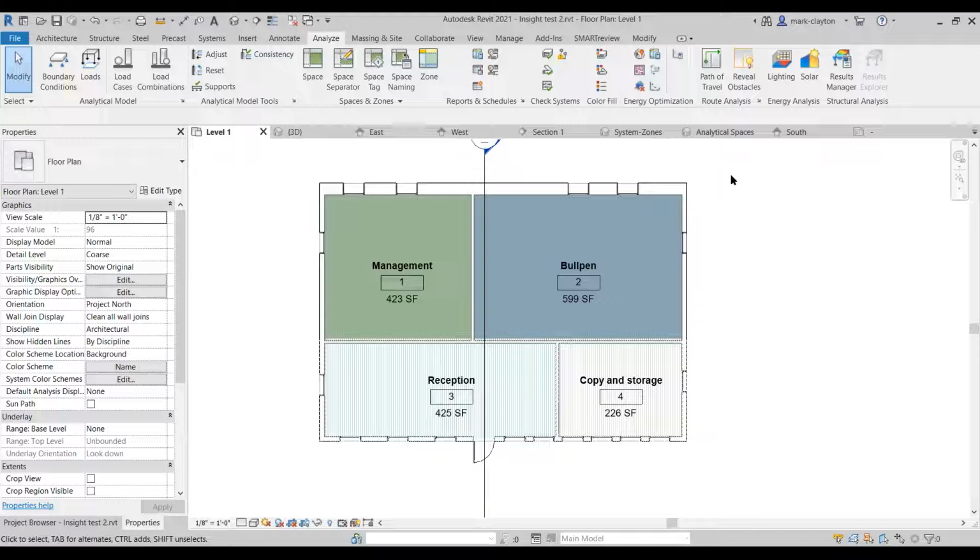Exterior type 1, exterior type 2, exterior type 3, or name them however you want. You could say exterior finish 1, plumbing. Exterior finish 1, non-plumbing. And then draw your building with those types.